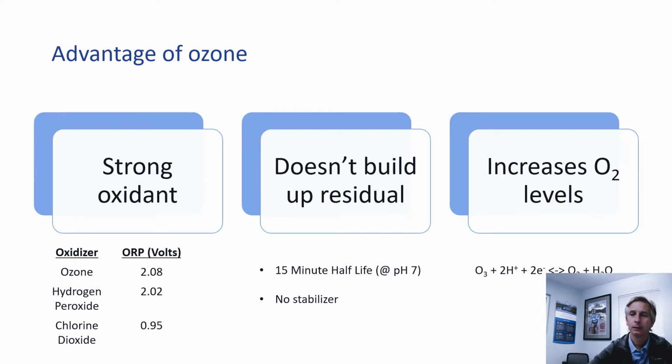in the disinfectant. So as the irrigation water is reused over and over, and the plants uptake the water and more disinfectant is added, that stabilizer, if they're from other disinfectants, can tend to build up in the water and cause two problems. One, it can have a direct impact on the health of the plants, and two, it can reduce the effectiveness of the oxidant if you have too much stabilizer in the system.